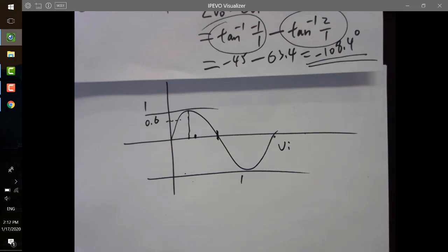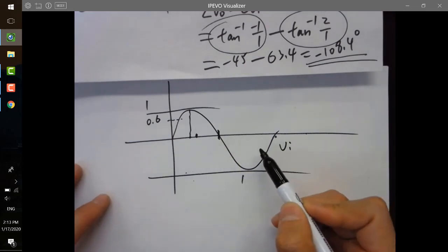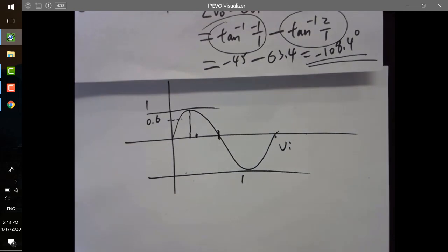It makes sense that it's always a negative number because your V out is going to have some time delay, so it's lagging, right? Yeah. But is there ever an example where it's leading? Yeah, it depends on how you define that. Usually when it's over 180 degrees, they treat that one as a leading signal because it's lagging too much, and because the signals are exactly the same. When you are treating it as lagging but it's more than 180, it's probably easier to just directly use it as a leading signal. That's what I'm thinking. But we probably don't have that much time delay in our examples. But that's a good question though.